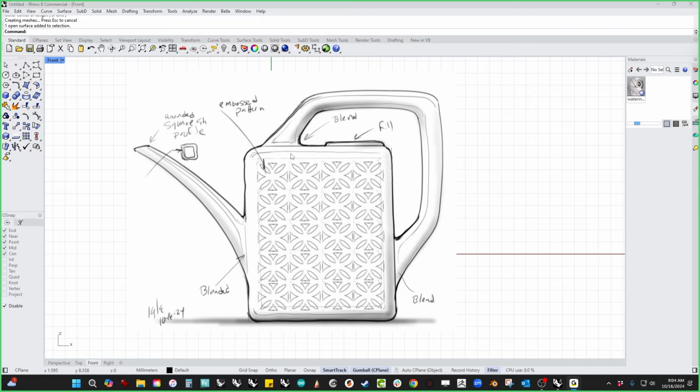You can't put a giant fillet on a tiny radius. You can't put a small radius on top of a big radius. There's an order that you have to do things. So we'll talk about that and hopefully give you some insight. In fact, we probably won't end up using filleting at all. We'll probably end up doing some manual blending in here because of the complexity of how this works. So I'll show you how we'll crash the fillet tool into the wall, and I'll show you where the wheels fall off, and then we'll talk about what to do.